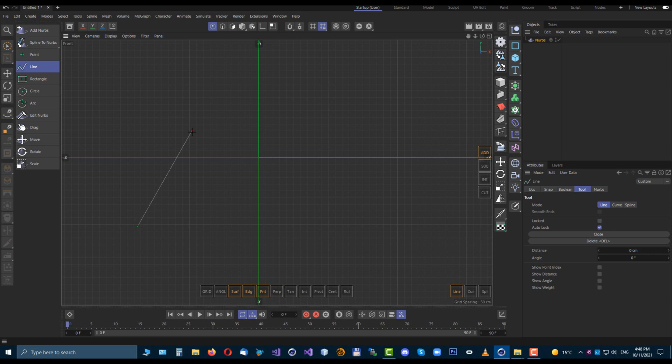With line tool you have in fact 3 different tools. First, in line mode you're creating lines or polylines. In second mode, curve mode, you're creating Nurbs curve with control points. You can also adjust weight of these control points now. So if weight is modified, then it is not B-spline but a Nurbs curve. If it's by default, then it is B-spline. And third mode, spline mode, it creates interpolation curve through the control points.